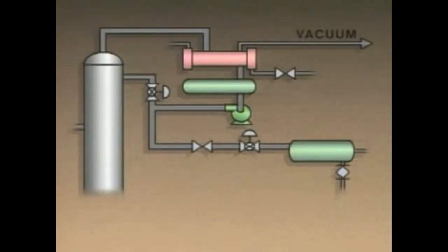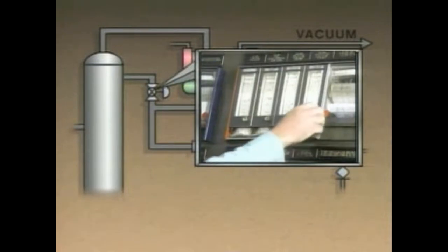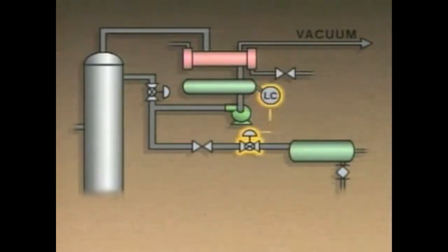To shut down the reflux system, a temperature controller is reset to close a valve in the reflux line and prevent overhead product from returning to the column. Then, the level controller on the receiver is set to reopen the overhead product takeoff valve so that the product that has collected in the receiver can be pumped to the overhead product storage tank. Once the receiver has emptied, the reflux pump is shut off to complete the shutdown of the reflux system.